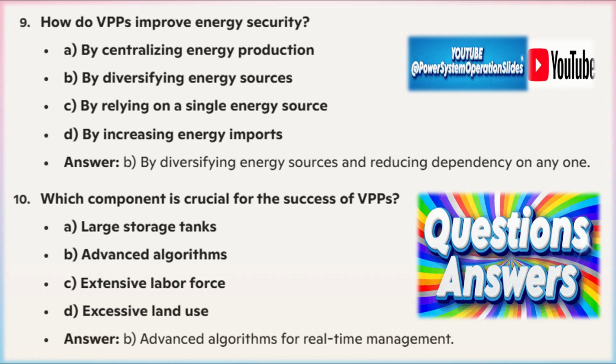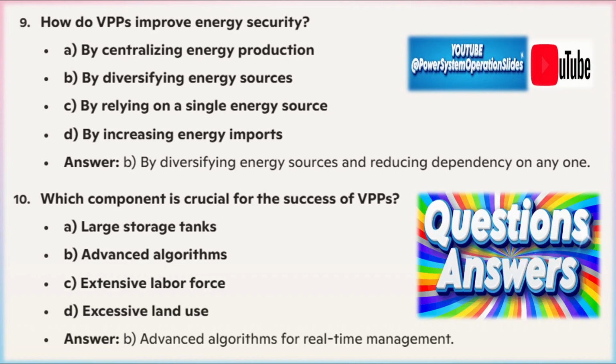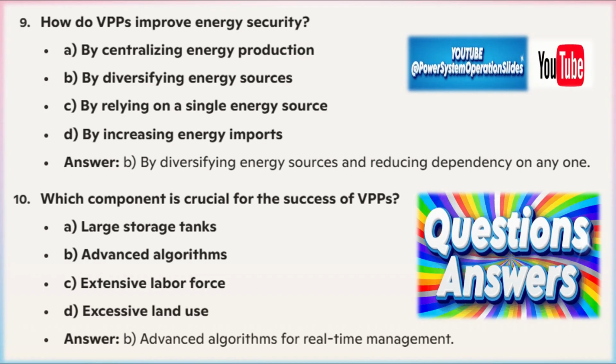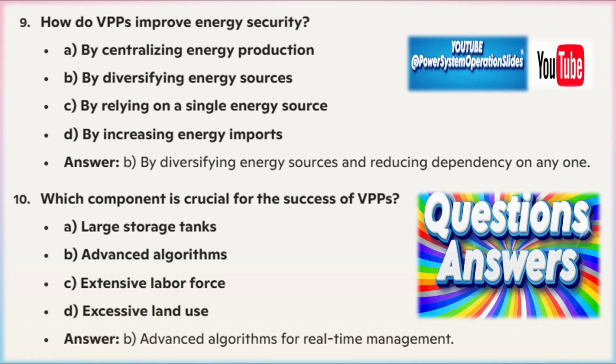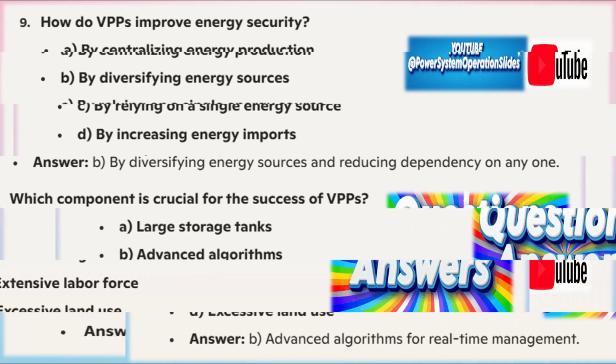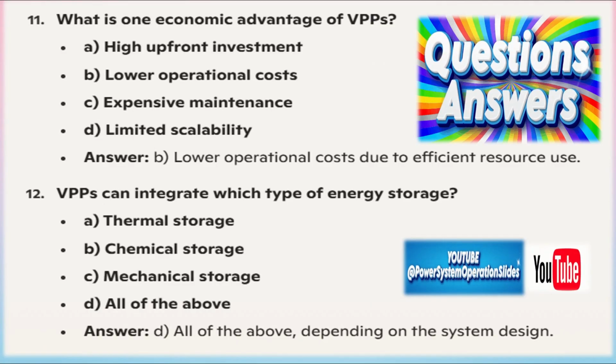Driving economic efficiency, cost savings. By optimizing DERs, VPPs reduce the need for costly grid upgrades and the expansion of centralized power plant operations. Incentives for prosumers. Participants in VPPs benefit financially by trading energy and flexibility, making renewable energy investments more attractive. Supporting the energy transition. Scalability. VPPs can scale with the increasing deployment of DERs, making them a key enabler of the energy transition. Innovation. They pave the way for innovative energy technologies, such as smart meters, dynamic tariffs, and vehicle-to-grid (V2G) systems.